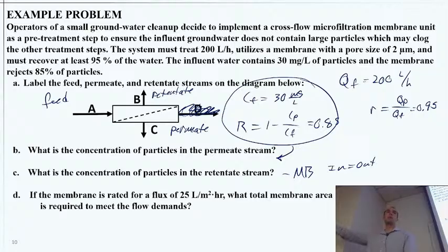And we know something about that Q out through the permeate, which will tell us what's Q out in the retentate. So we could say something like QF CF should be equal to QP CP plus QR CR. All right? And you should then have enough info to solve the rest of it. So the mass balance strikes again, but in a very simple form.